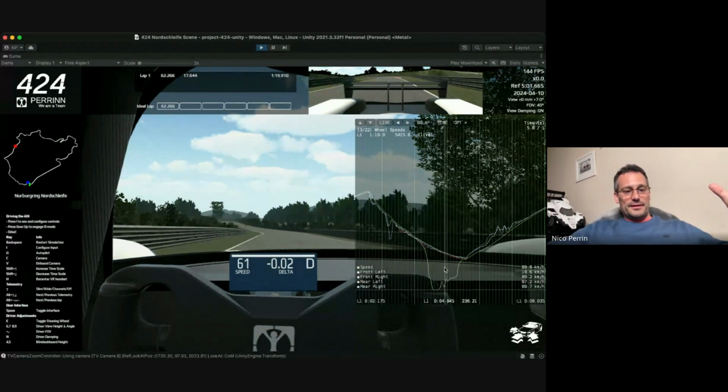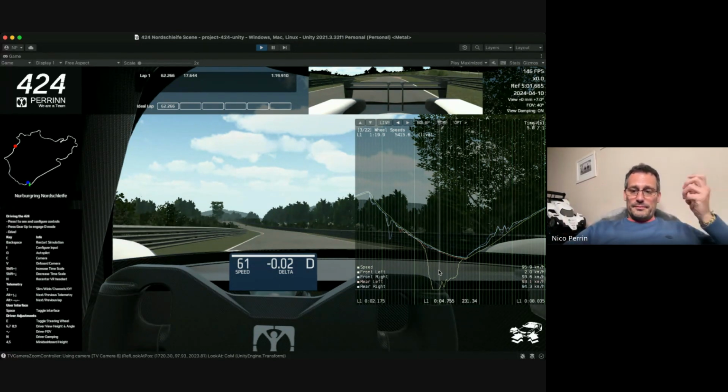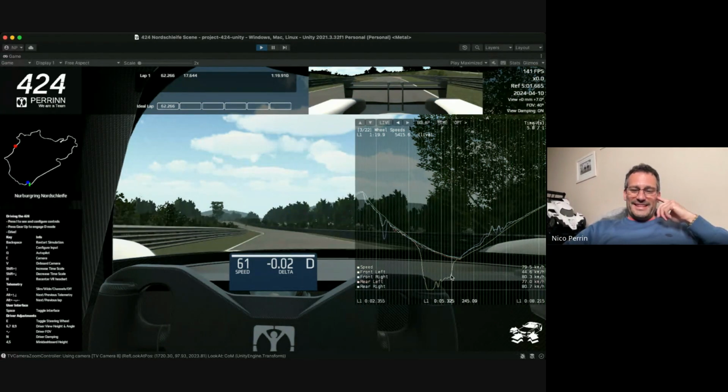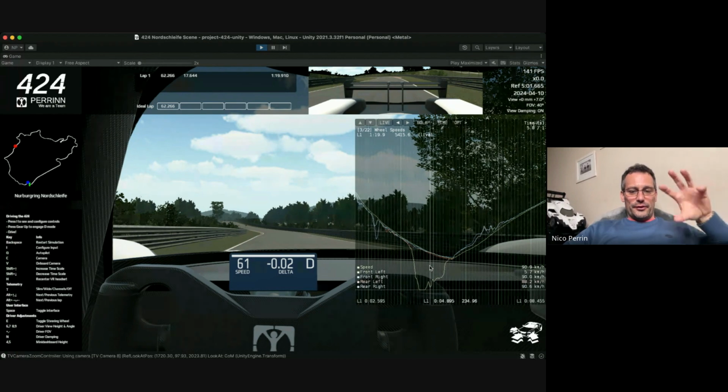He can see it. It's harder in a car with bodywork on top, but he will feel it in the steering wheel. And the way he will feel it, and if you drive the simulation, you do feel it, is the steering load is getting a bit lighter because one front tire has lost the grip. So you feel it in the steering. So that's a problem. But this is typical of turn 1 because of the amount of bumps as well. The other corners are not as bad.